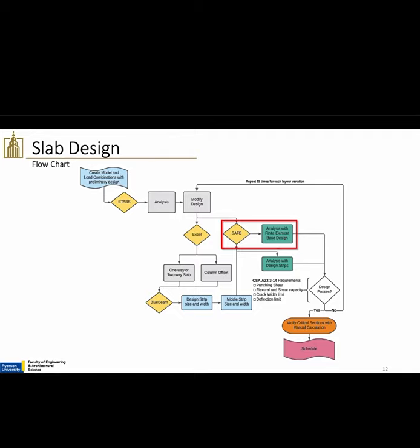However, to validate the slab designs, we opted to hand calculate the column offset and identify one-way or two-way slabs. This data was exported into Bluebeam, where the design strip and middle strip sizes were established. These were used in SAFE to run a design strip analysis.